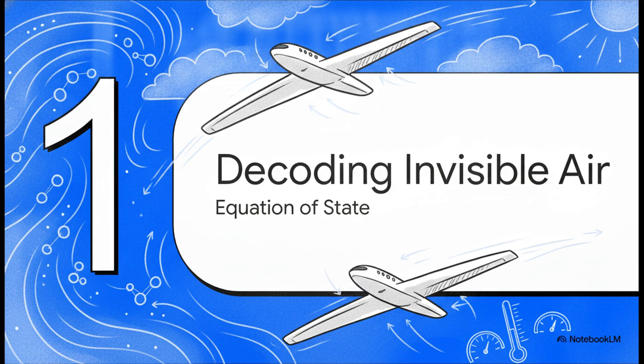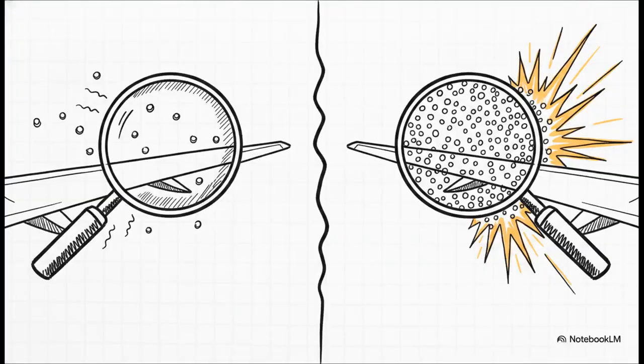Let's get right into defining our atmosphere. The master key to understanding the atmosphere is this single, incredibly elegant formula, the equation of state, P equals rho R T. But let's step away from the math for a second and look at the physical story happening here. Pressure, that P, is literally the physical force of millions of microscopic air molecules violently slamming into a surface, like the skin of an aircraft. Density, or rho, is simply how tightly packed those molecules are in a given space. And temperature, T, well, that's just a measure of the speed of their chaotic motion.